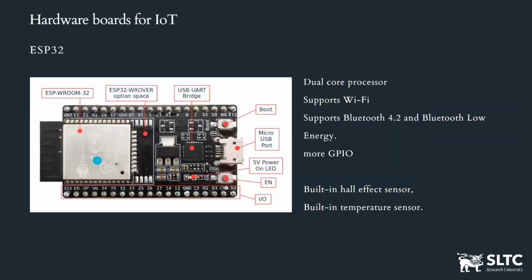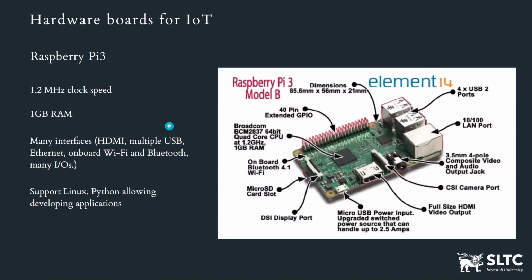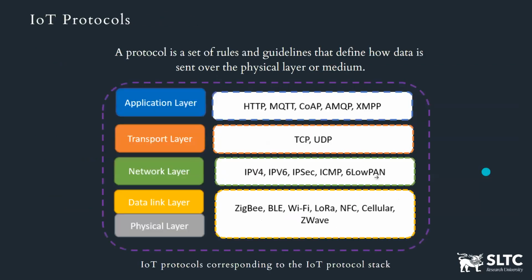So when you compare with the ESP microcontroller, Raspberry Pi has more clock speed, right? You can check the memory space as well. I think Raspberry Pi has more memory space than ESP32, and many large algorithms and image processing algorithms can also be run in a Raspberry Pi model.